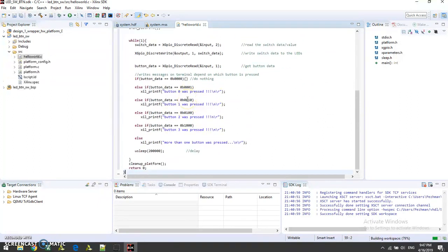After this, we have to connect our ZedBoard to the computer and turn the board on. We need to make sure that two LEDs, one of them is P good and the other is done, are both switched on, and in that case we know that the board is functional and everything is fine. Also make sure that the JP5 on your board is set on JTAG. The next step is to program the FPGA by pressing this button.